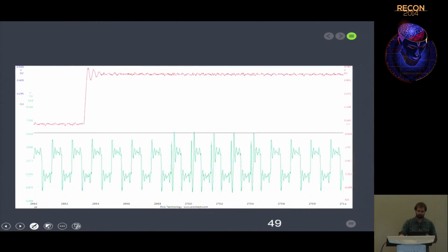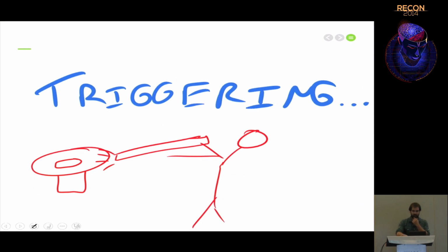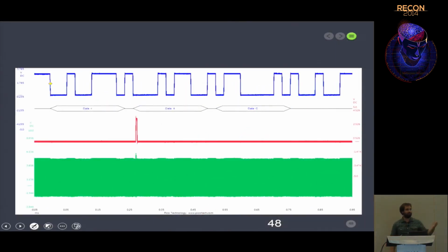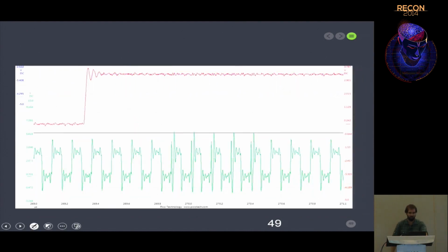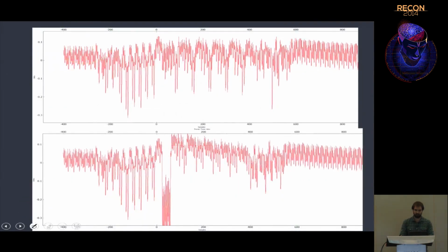You can also do stuff like, the ChipWhisperer does support glitching on a digital data pattern. So this is a glitch being generated based on a UART byte going over the wire. When that UART byte goes over the wire, you can see it's then inserting 5 clock glitches in this case. So it is a very real threat to systems. So let's try the clock glitching demos. These are a little more sketchy.